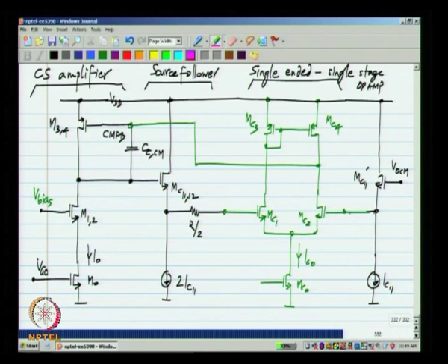Another way to think about it is that there are too many stages in the feedback loop. So, there is a lot of parasitic delay. One of the delays has to dominate, and that is what we call dominant pole compensation. So, the feedback has to be closed around a single stage, and that can be done by using this capacitor. So, any way you think about it, essentially you will have a single stage in feedback.